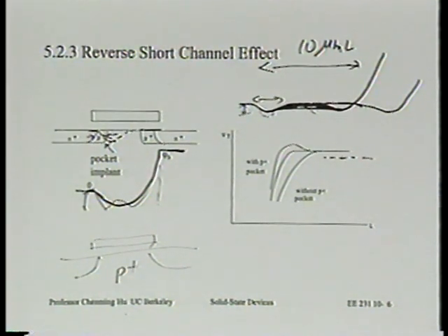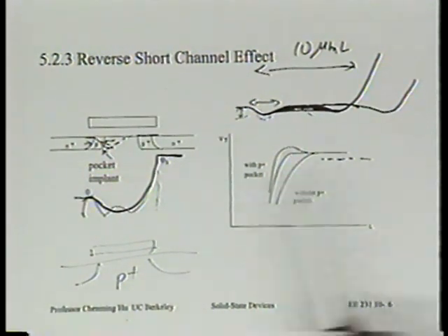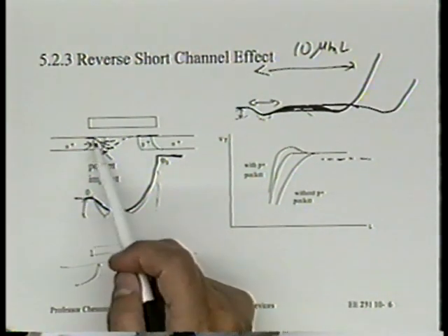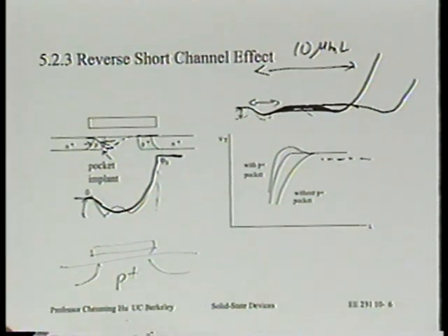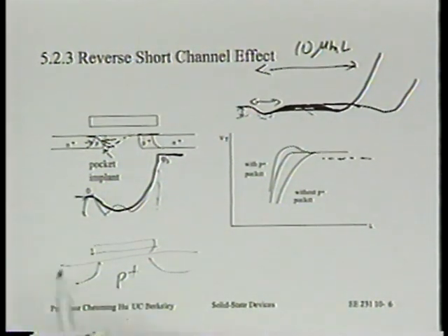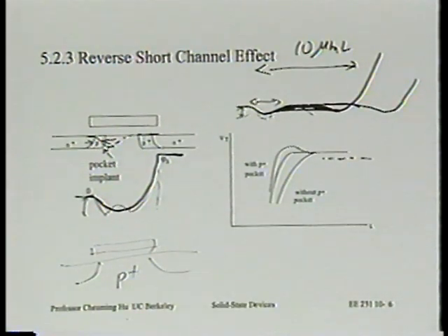And we'll probably spend enough time, so I don't want to get more. But if you don't think this way, you probably will think about some questions that cannot be answered by just thinking of them as three transistors in series. One very simple question really is, if you have three transistors in series with 3 VTs, why should the threshold voltage increase as L decreases? Why doesn't it just stay at the highest of the 3 threshold voltages? You see what I'm saying? So you have to believe that even the barrier at this region is getting reduced just by making the channel longer or smaller. All right?